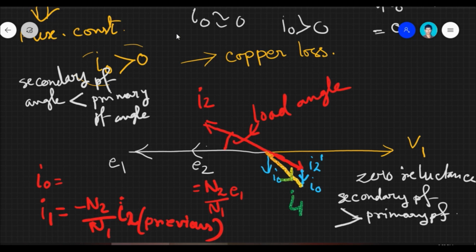That means now the primary of the transformer is operating with a poorer power factor than that of its load. If the load power factor is 0.5, then it will operate with a power factor of say 0.4 or 0.3, something like that. So that is not a good indication for a transformer, and that whole thing is coming due to this consideration when we remove that idealistic assumption that reluctance is very small.